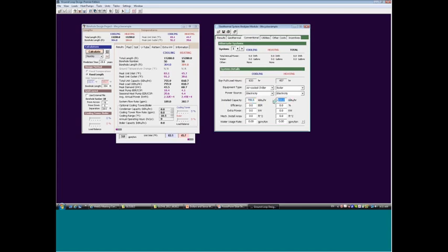So the total load being covered by the geo system and the conventional system are the same. I can choose 2 types of conventional systems. I'll choose an electric air-cooled chiller, for example. I'll just choose a natural gas boiler. There's a range of options. What we put in here is our predicted average efficiency of that system.